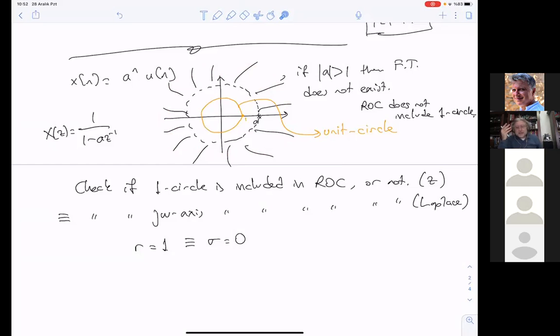So the Z transform is a generalized version of the discrete Fourier transform. Even for unstable or non-convergent series, you may still have the Z transform expression, which is like this, but the region of convergence is magnitude of Z greater than A. We will continue with several more examples, but this is the generic way of putting the Z transform.